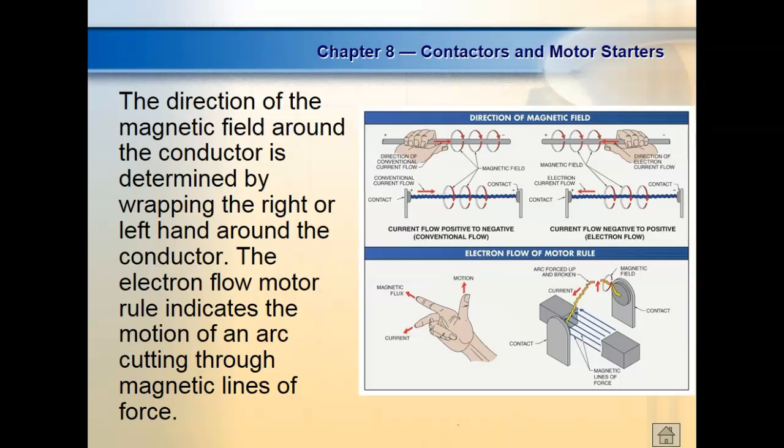This guy right here is swapping polarities 120 times a second, because it's 60 cycles. 60 cycles is made up of one positive alternation and one negative alternation. So it actually swaps direction 120 times a second. That's 8.33 milliseconds that it swaps directions. If y'all don't know engineering notation yet, it's 0.0083333 seconds.